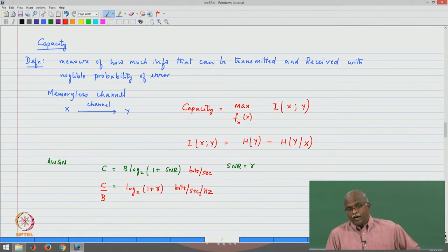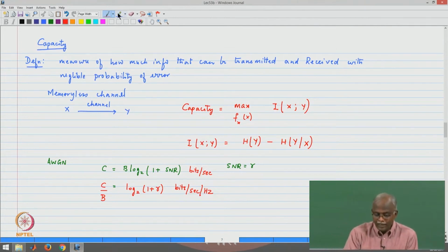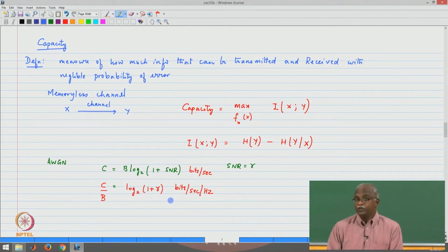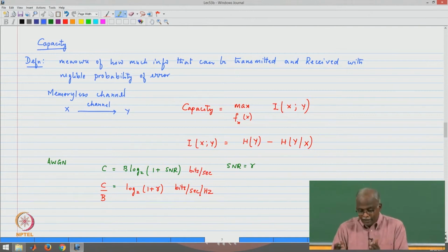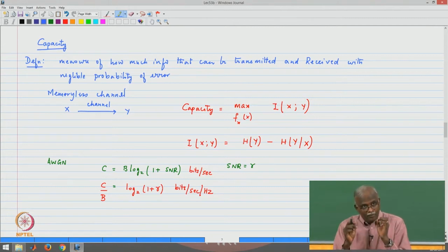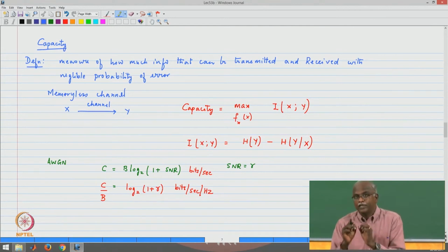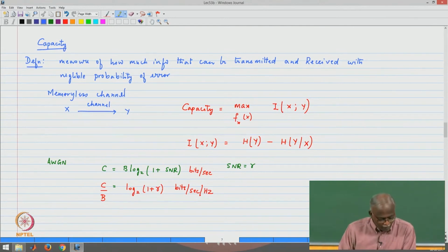Okay. So, that is our basic definition of capacity, derived from first principles using the definition of capacity in terms of mutual information and entropy, and this is what we often refer to as Shannon capacity. This is the expression that we have used quite extensively when we were talking about the capacity of a wireless channel, when we had one transmit antenna and one receive antenna. Now, we are going to extend our understanding to the case where we have multiple transmitters, multiple antennas.